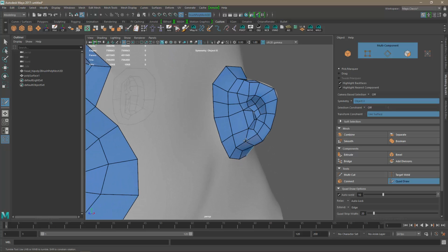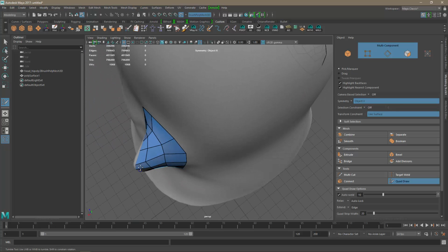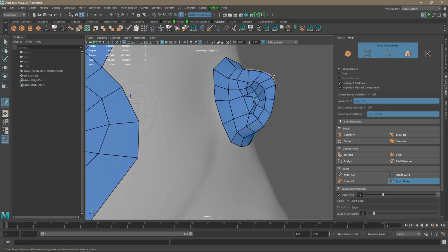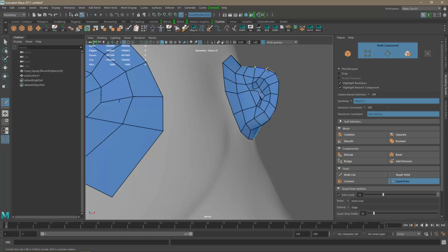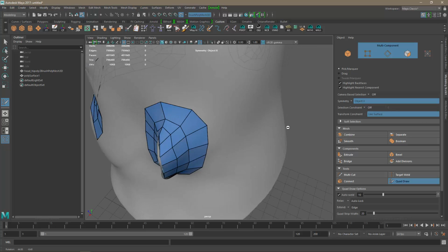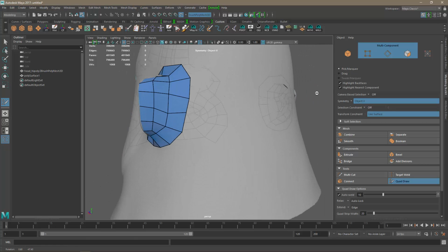So I kept the quads, and I also kept this shape, and maybe I want to move this a little bit more, but when I subdivide this mesh, I will have more polygons to adapt to the underlying high poly, so I'm not too concerned about these borders not following exactly the shape of the ear in this case.